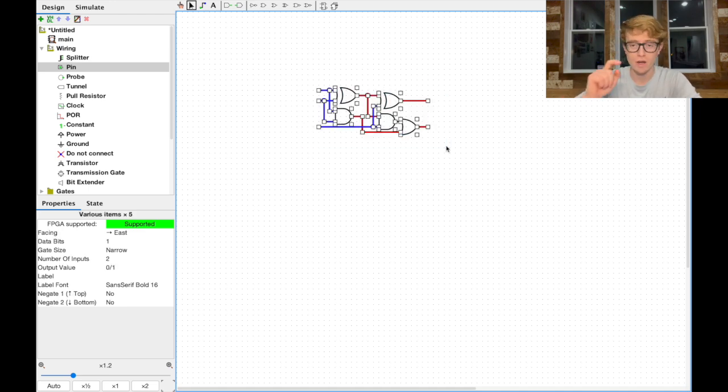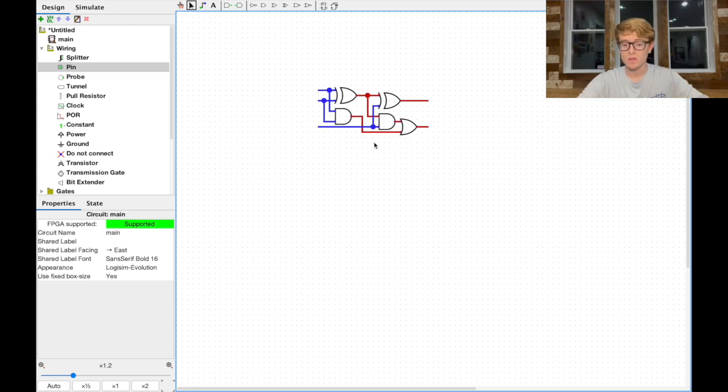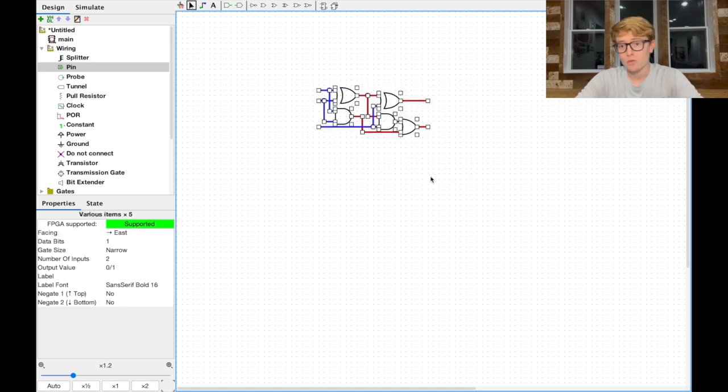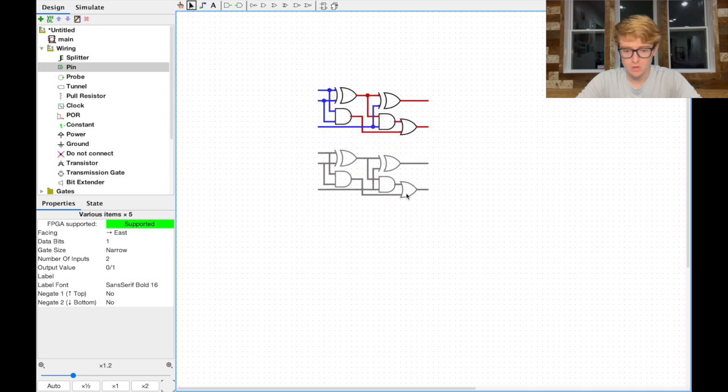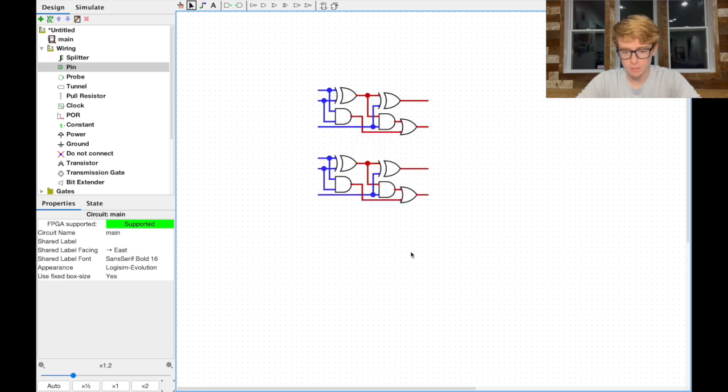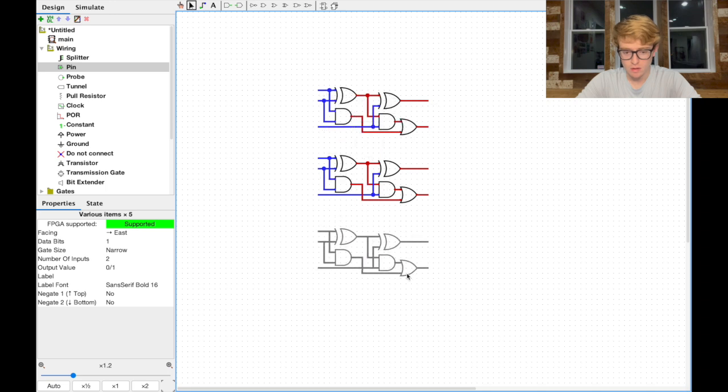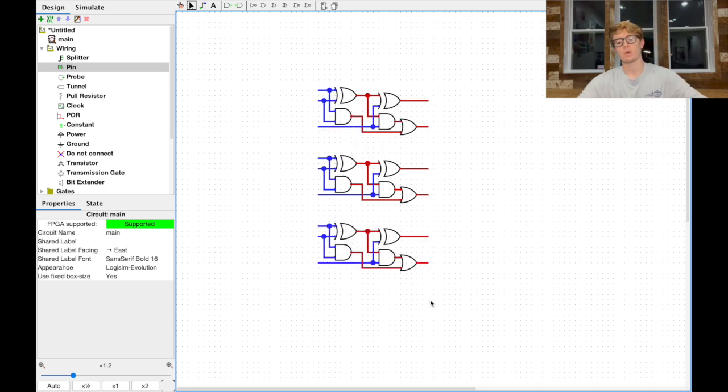So we'll go from 0 to 7 every time we push the push button. It'll increment and it'll reset as soon as we go above 7. So what I'm going to do is highlight my half adder. I'm going to need 3 of them, because remember, this only adds these 2 bits plus the Cn. I need 3 bits. So I'm going to need 3 full adders. So I'm going to highlight this entire thing, Command C, Command V, and drag this thing down. And then I'm going to grab another one, Command V, pull that thing down. There we go. So now I've got 3 full adders on the screen here.